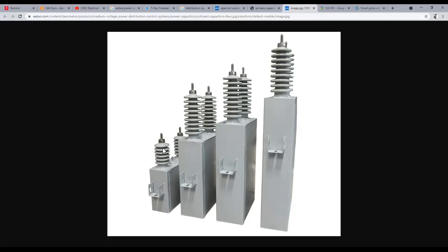Now, we tell manufacturers, hey, when you ship us your capacitors, short them for us. And usually that's how they come. But if a set of capacitors comes off a truck and they're not shorted, what do you need to do? You short them. Short them with what? An insulated conductor. And what are you going to wear for protection? A rubber glove. Yeah, put your rubber gloves on and use all your safety gear.